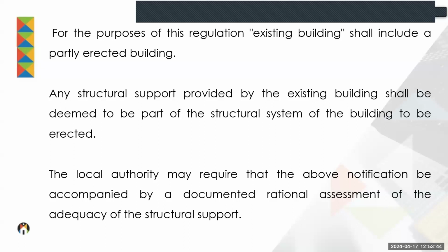So in this case, the engineer must make sure that that existing wall or column, which now becomes part of the new structure, is of sufficient strength to carry the combined loads of the existing as well as the new portion of that building to the foundations, to be dispersed into the ground.